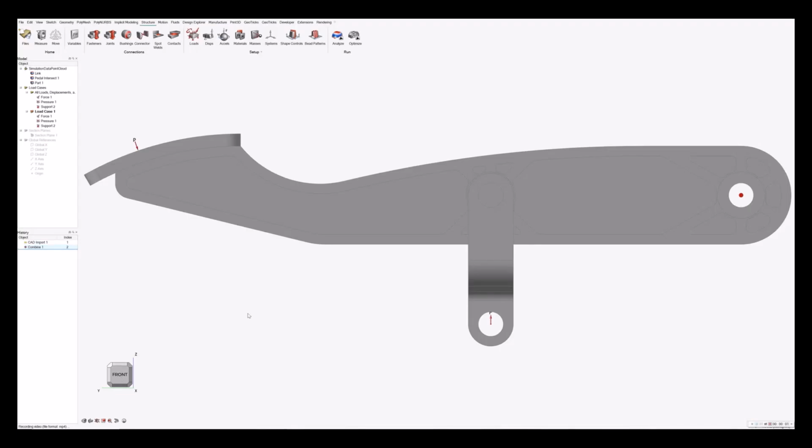In this video, I'm going to show you how to create a point cloud from simulation data and then convert this point cloud into a field so that it can be used in field-driven design so that you can add gradients to lattice geometry. I've started by creating this model here, which is a brake caliper from the automotive setting.